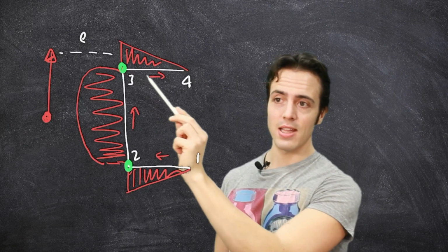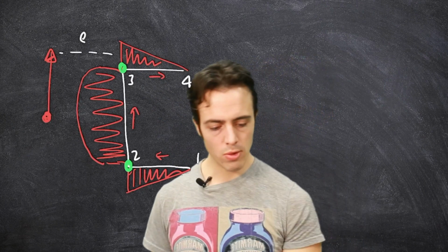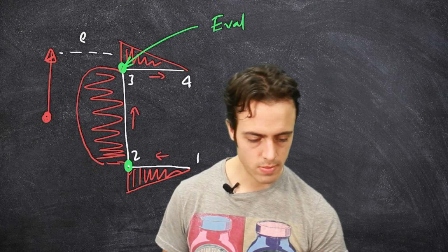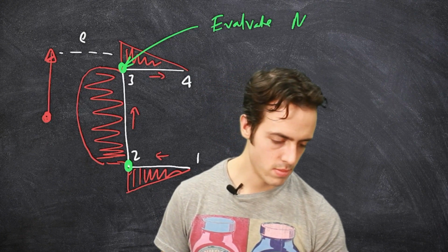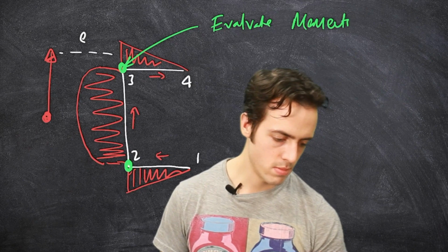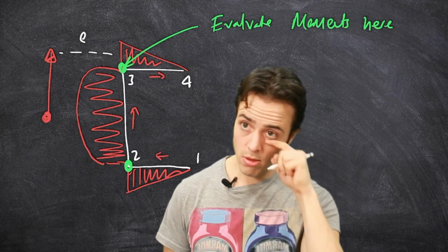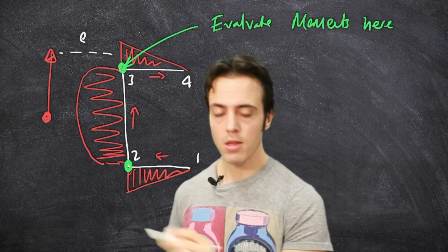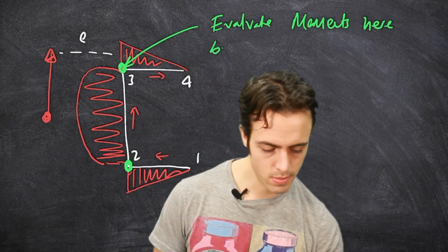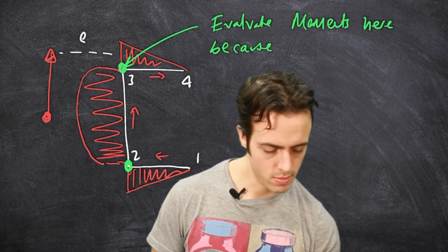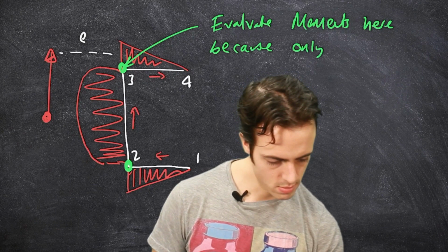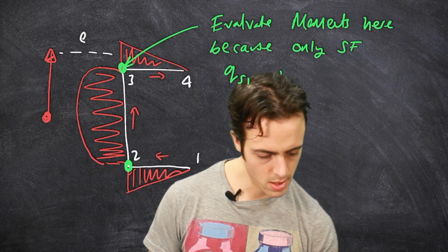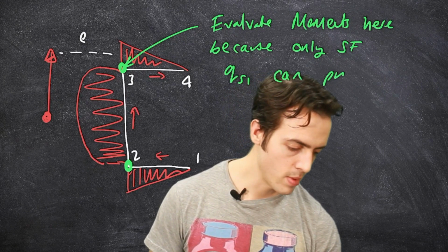And this one is exactly the same. So I'm going to choose to evaluate moments here, because then we only need to care about this one shear flow. Only shear flow QS1 can produce a moment.